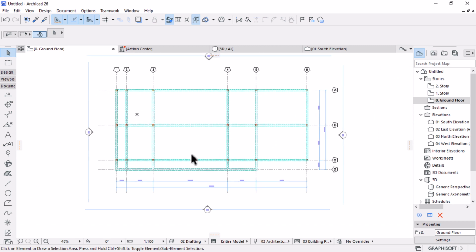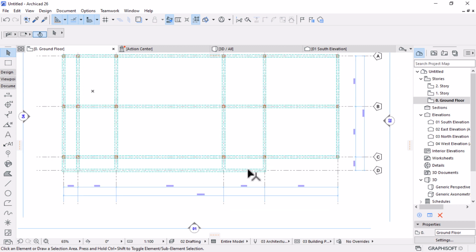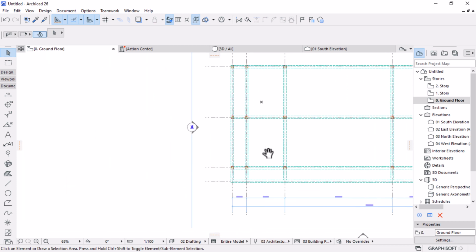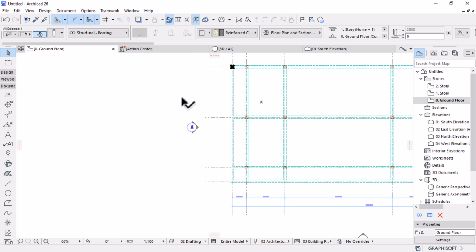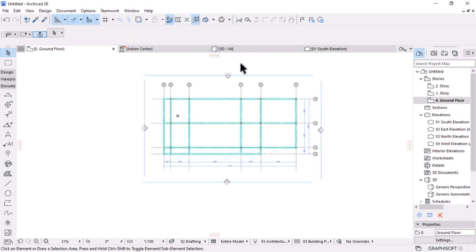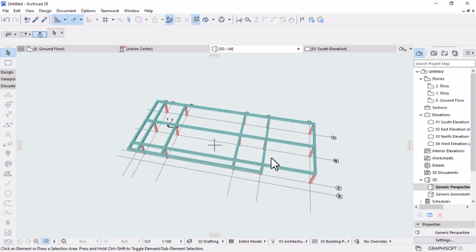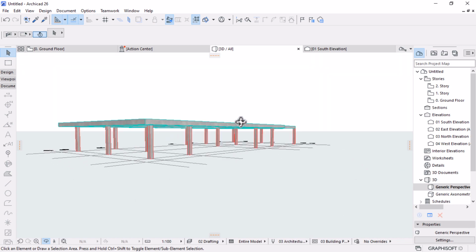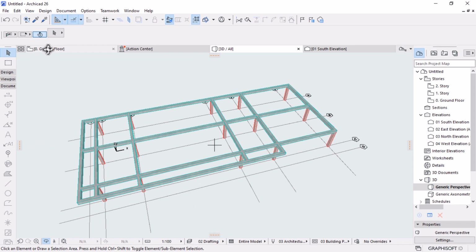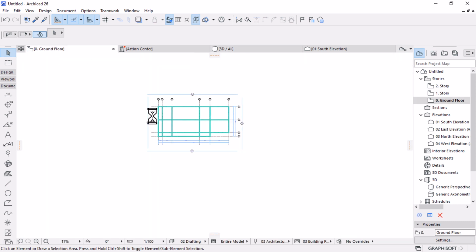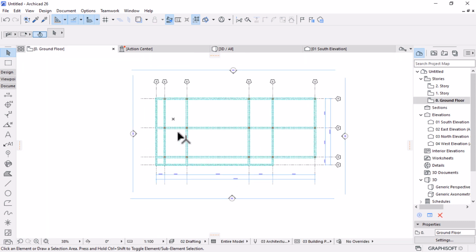Okay, and then because we're gonna have a suspended kind of curtain walling this side, and then this side we don't have columns as well on this area, something like that. If we check on 3D, this is basically what we have. Okay, so I would come back, and now is the time to do the floors. So let's come here under design and activate the floor slab.